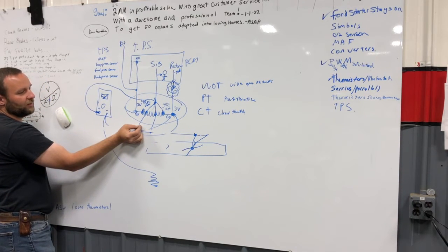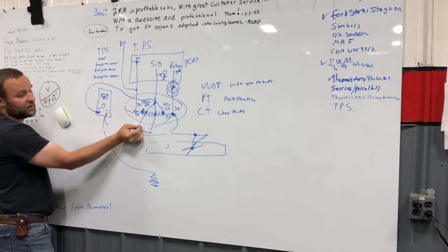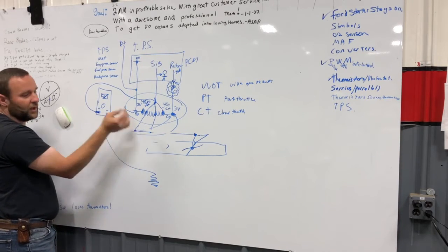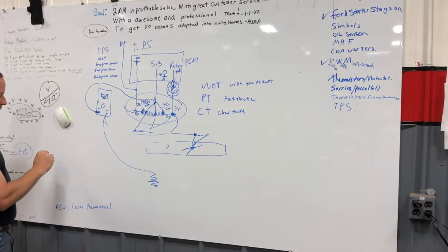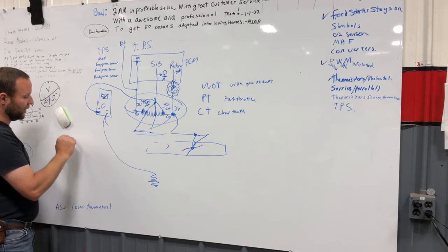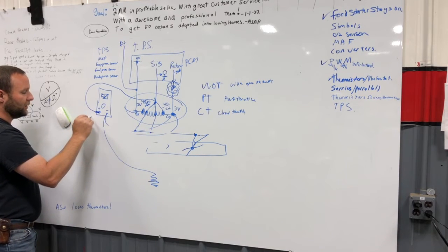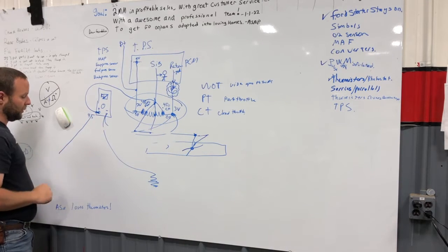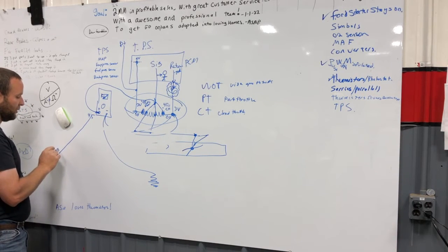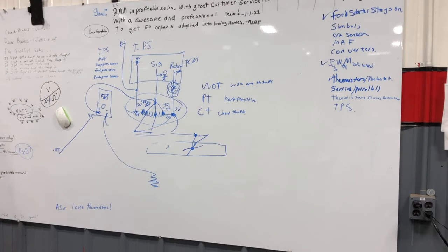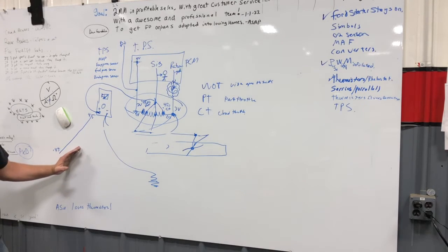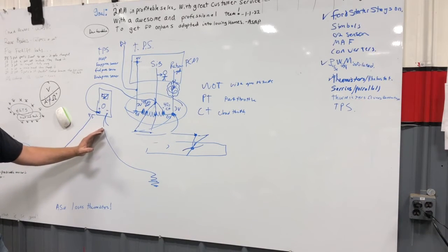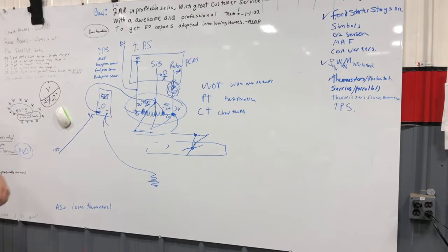Oh, it goes to 0 volts. That's a problem. It should never go to 0 volts. It should never drop out. As you move it, it should consistently go up to 5 volts or 4.5 volts. That makes sense? Yeah. If it drops out at any time when we're hand moving that thing, it's bad, as long as we got good back probe wires and we're not losing connection.